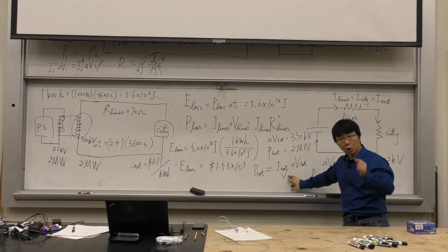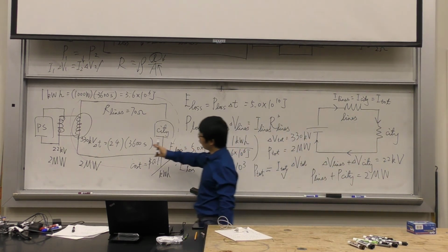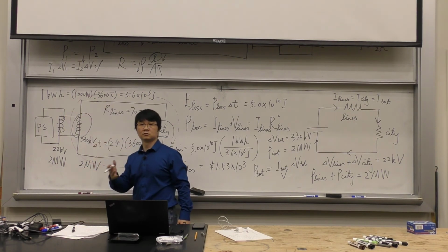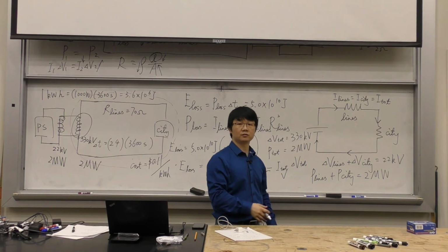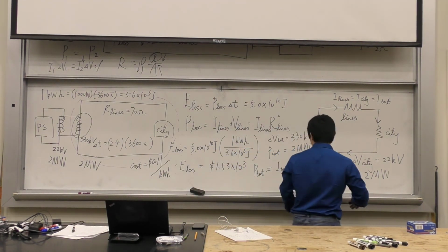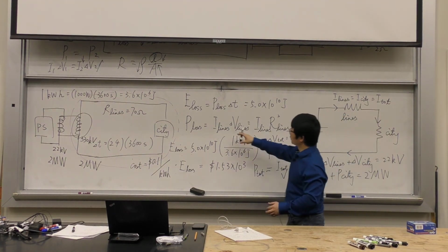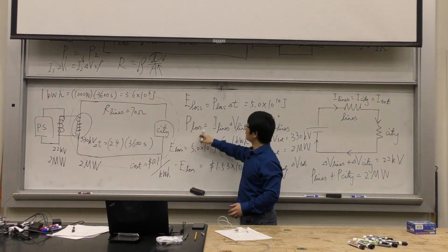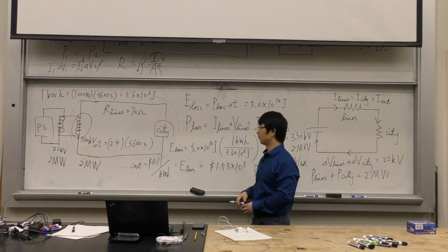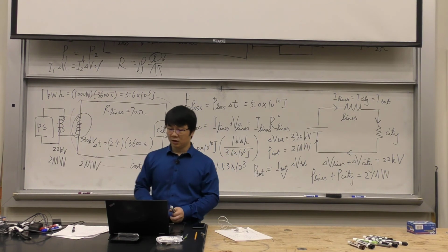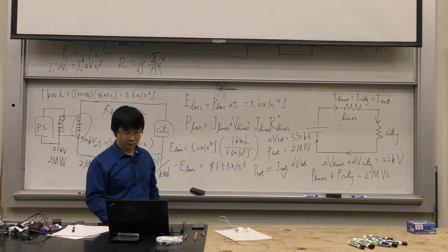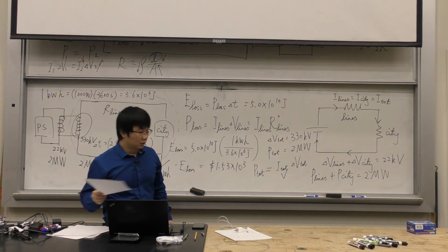So you're going to find a lower I total, which is a lower current going to the transmission lines. That's our goal, right? We want to reduce the current on these transmission lines so that the energy loss will be reduced, okay? And once you have this I total, you're still going to find the power loss and multiply this by the time to find the energy loss, okay? So you just repeat the same steps with this new voltage after the transformer. Now you can pause the video and do the algebra.